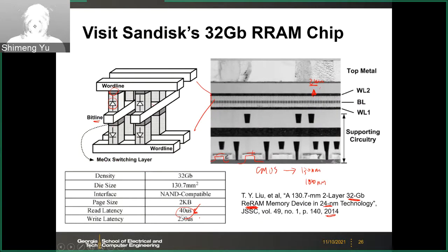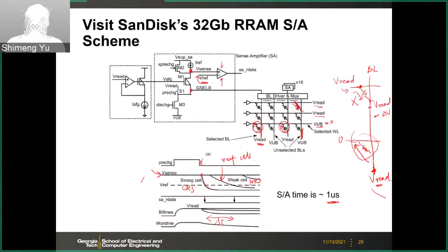Because we shared those sense amplifiers, you have to borrow a sense amplifier from another array, which is far away. Then there will be parasitic RC delay, making the total latency large. So I would say this is not a perfect design for this particular technology. One of the limitations is that the peripheral circuits use a very old technology node, therefore limiting its area and also performance.